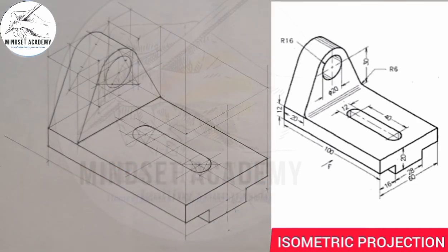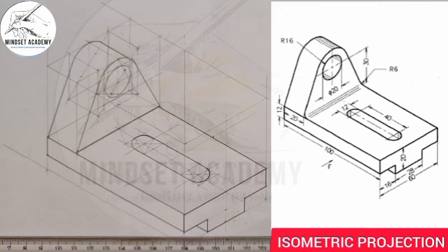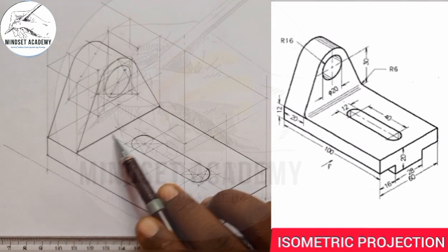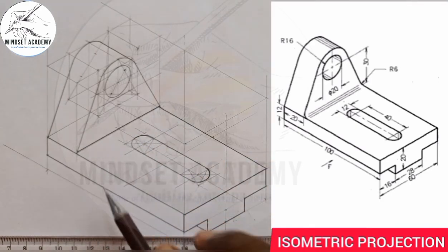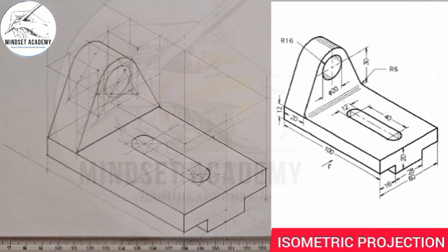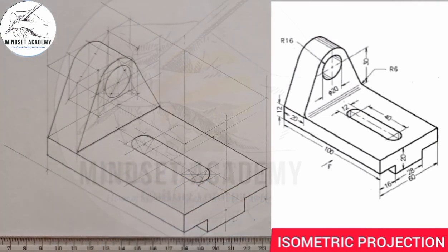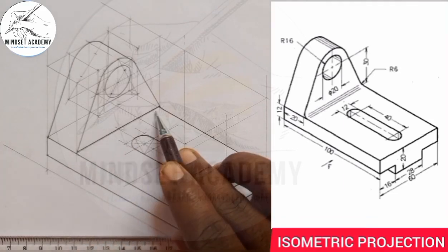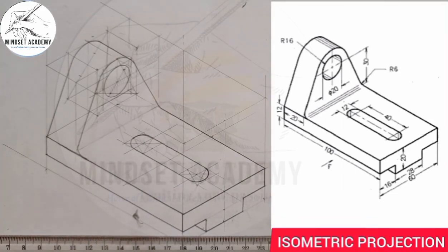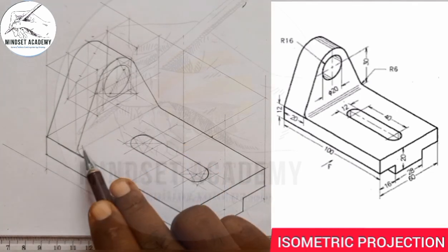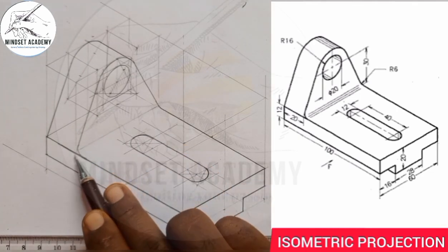Can you see that? Now, even though you look at this line here, from the diagram it is not really there, right? I'm going to delete this off. This is only a fillet of what? Radius of 6. So that's what I'm going to do now. So first of all, remove this away. So this is what we have here. I've removed this line and I've replaced it with what? A fillet of radius of 6.